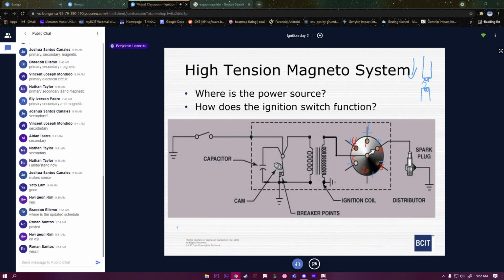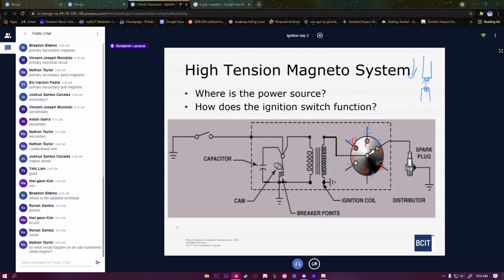Okay, so back to what I was saying. Every 100 hours, we're going to take the spark plug out of number 1 and put it into cylinder 6, and the one from 6 and put it into 3, 3 into 2, 2 into 5, and 5 into 4. Does that make sense? That rotates it, like rotating the tires on your car. You take the front tires off and put them on the back, and you take the back tires off and put them onto the front. And then the fact that your tires on the front of your car wear out faster than the tires at the back gets evened out.